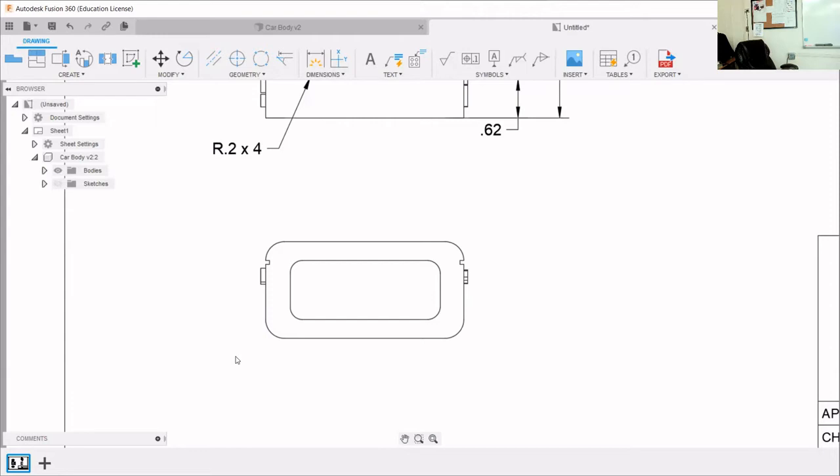In the middle, the height. Okay, so this is a cutout, right? This is a hole that's been cut out. So we'll need this dimension. We'll need this dimension. You're going to need the radius of the internal fillets and the radius of the external fillets because it's 2 different numbers. We also need to know this hole, is it centered?